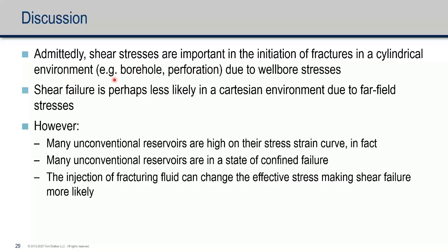And when you're in a cylindrical environment, it's not the same as if you're in the far field. So you're in these cylindrical environments with borehole deformation, with perforations that are circular, and you have to contend with wellbore stresses. But as you propagate away from the borehole or the perforation, shear failure is perhaps less likely in the far field.